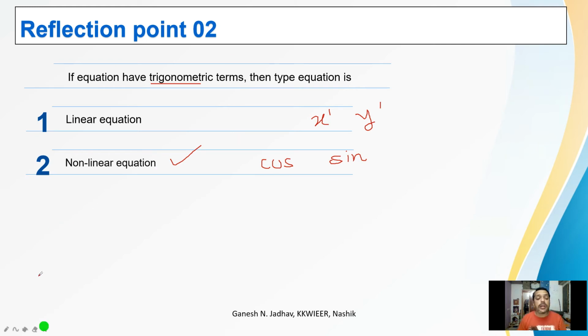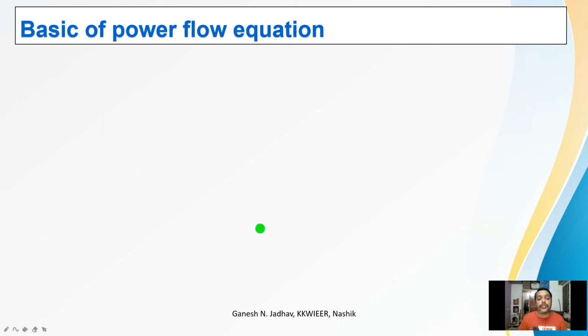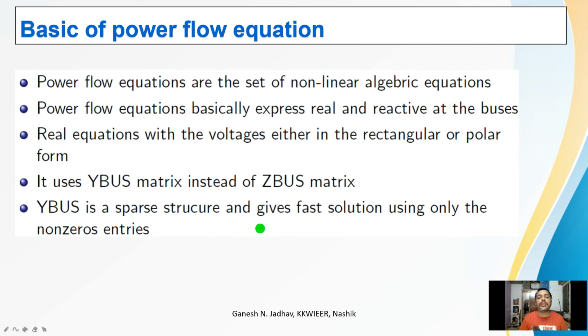Why am I discussing this? Because all the load flow equations we are going to see are of this type. So let's begin with the basics of the power flow equation. The power flow equation is a set of nonlinear algebraic equations. So it is not a linear equation, it is a set of nonlinear algebraic equations. Hence we have to apply the methods of solution of nonlinear algebraic equations.